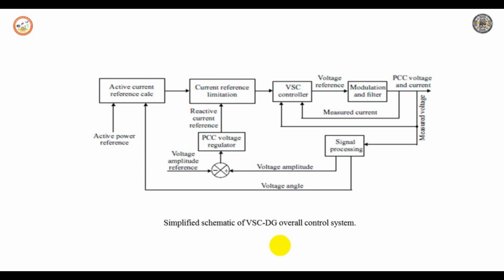Here the control reference limitation block limits the overvoltage. It is assumed that initially the converter is injecting a current vector A, which means only active power is injected. The quarter circle in the figure represents the maximum allowed converter current.